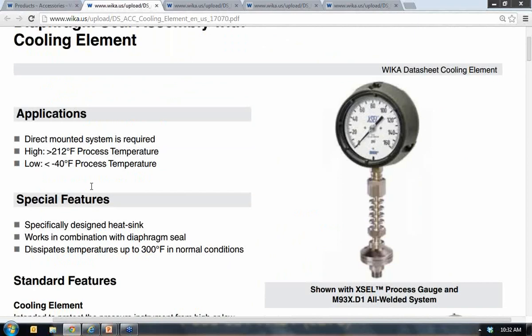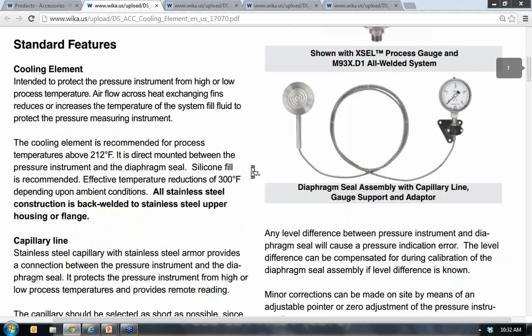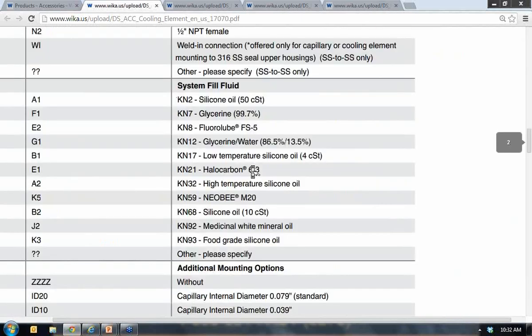Exactly. All right. The next question is: are the fluids that are used to fill gauges treated with an antifreeze, or does that have to be specified? So, when we talk about glycerin, any ideas to what sort of temperature typical glycerin can go down to? And then maybe you should talk about the other fill fluids that we can put in gauges for dampening, like silicone, to see if they can get down to lower temperatures.